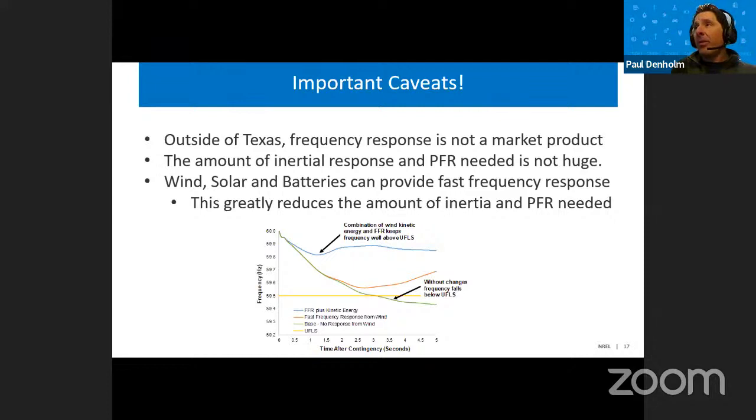And if you've got hydroelectric plants and other renewable resources that can provide these services via synchronous generators, such as geothermal, they're going to compete against you. But I think the biggest challenge, of course, is that wind, solar, and batteries themselves can provide alternatives to traditional physical inertia and traditional primary frequency response, particularly because they can react so fast and provide something called fast frequency response. And we have done a bunch of simulations where if you enable fast frequency response from wind and solar, it can provide a substitute for traditional physical inertia, and kind of, again, digs into that opportunity for CSP.